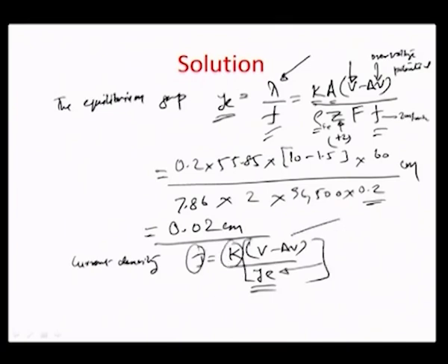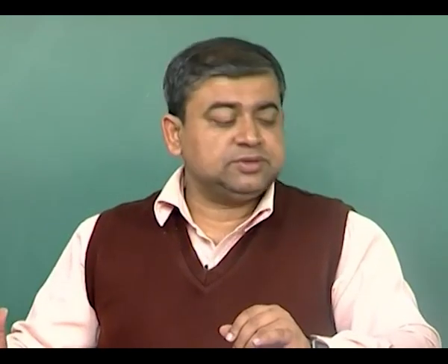Okay. The total voltage which is available after taking care of all the different anodic overpotential due to migration effect, all those things together, as we illustrated before, is delta V. So effectively available voltage between the two electrodes which can do machining is V minus delta V, and so the current density, which is the ionic transport between the two electrodes, is actually equal to the conductivity times this available voltage per unit the equilibrium gap YE, which is there between the tool and the electrode.